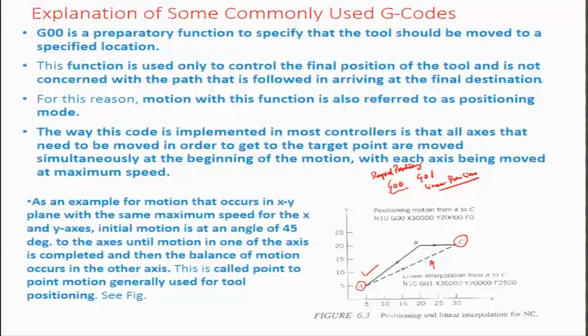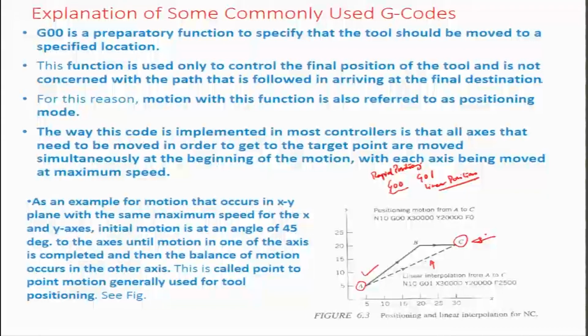So, when we are talking about this path definition through two different coordinates, namely the x and the y coordinate, what we mean is that there are two different spindles, one in the x direction which has a motor which will rotate and execute different values of x, and another in the y direction which will execute different values of y. So, supposing the motors were to operate at full speed, then obviously the x will always be equal to y in that situation. However, the point C, as you can see in this figure, may not satisfy that criteria where x is equal to y, because C is slightly more towards the right on the x than on y if they were to move equally with respect to each other.